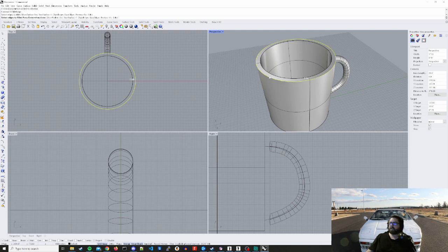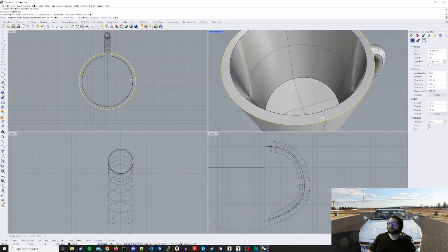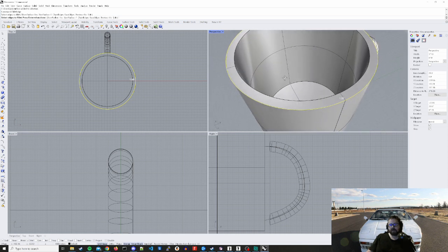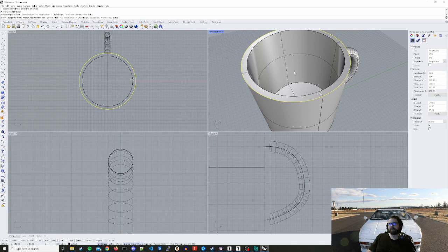and we're going to just select the cup. Now, 1 is not very much. That's a pretty small amount considering that this is technically a 10 millimeter edge. So what would be more reasonable? Maybe 2. If you just put the number in, it's going to know what you're doing. So we just hit 2. And you can see now up at the top where it previously said next radius 1, it says next radius 2.